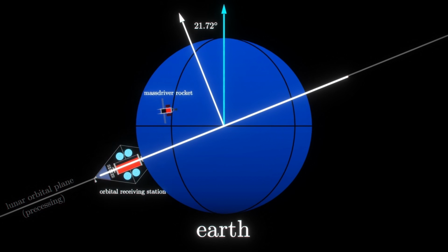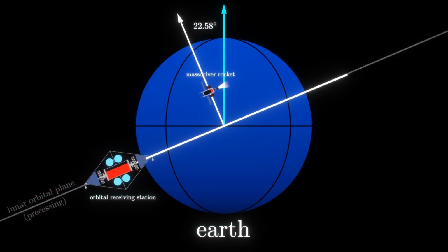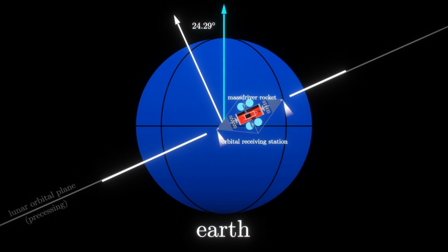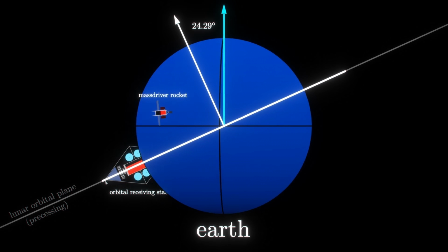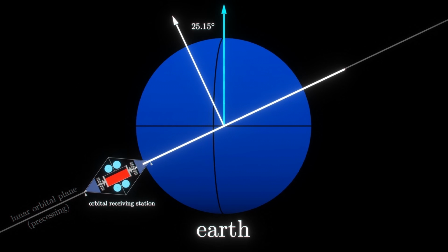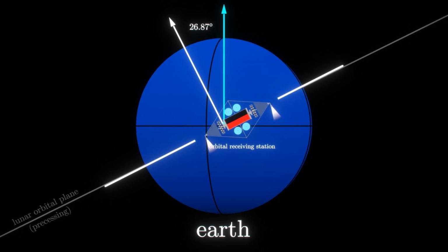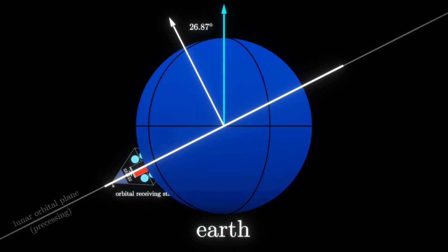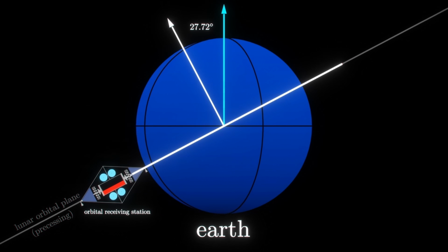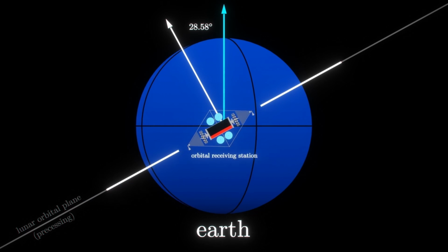That is very manageable, especially for a station constantly receiving incoming rocket pods, which should arrive with unused propellant margins, giving the station a nice reserve for orbital maneuvers and everyday station keeping, even if it's low-grade performance lunar ISRU-derived propellant. So by having the station undertake this slow and gradual inclination change to track the lunar nodal precession, we maximize the quantity of alignment periods it gets with the lunar orbital plane, and thus the average delta V required for a transiting rocket. And here I should note we're assuming a circular orbit for the time being, since it simplifies the planning of rendezvous.